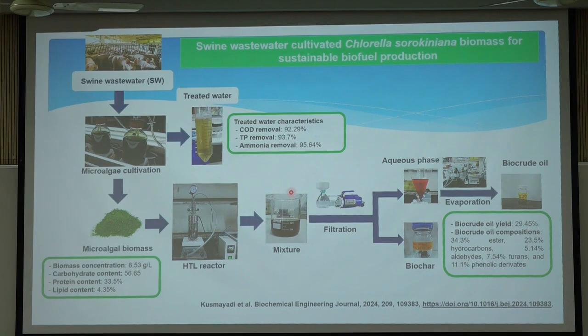Yeah, this is another study. We found that the COD can be removed by 92% if we use the stream wastewater in the cultivation of the microalgae. And then the total phosphorus can be reduced by 93%, then the ammonia can be reduced by 95%. So all of this can be nutrients for the microalgae. Yep.